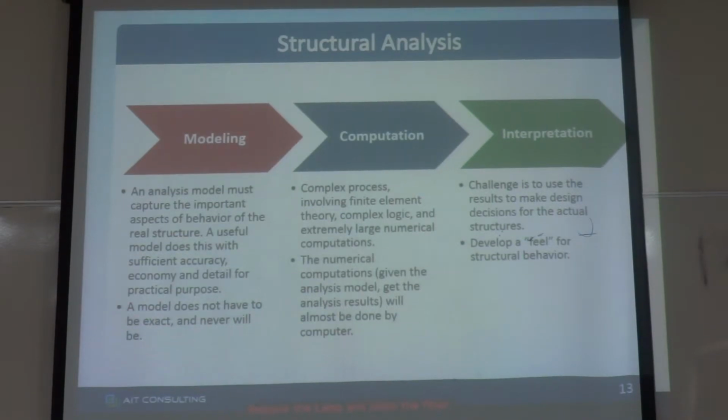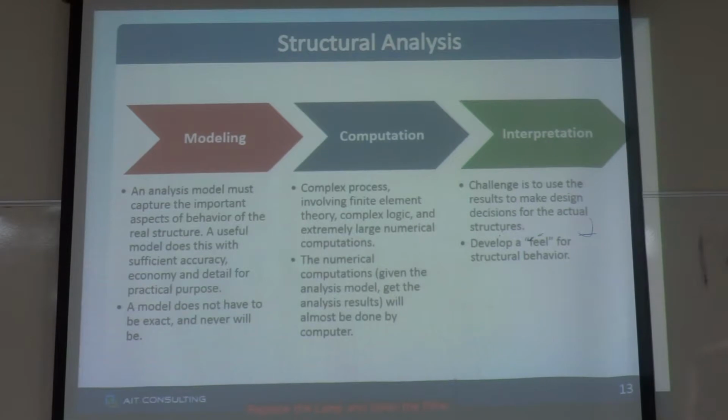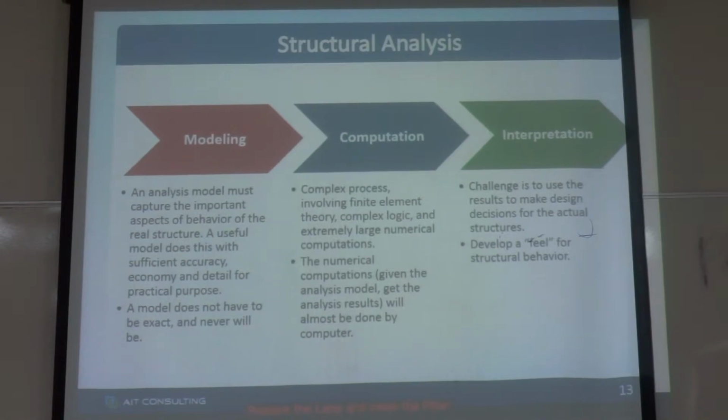So when you check the forces and diagrams, and you understand the behavior, if the forces are not correct, you have to recheck your model, revise your structural system, and do the analysis again.